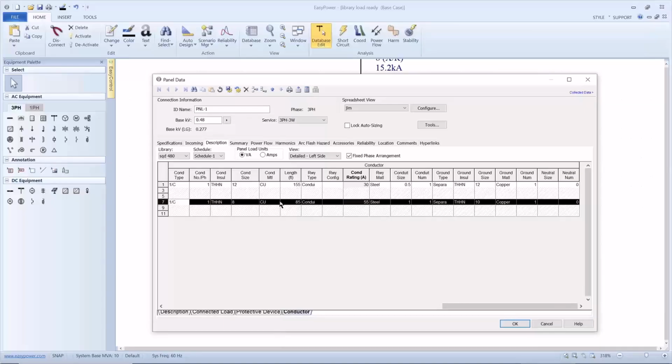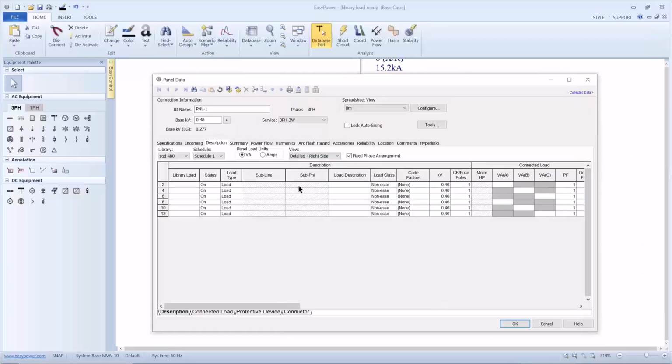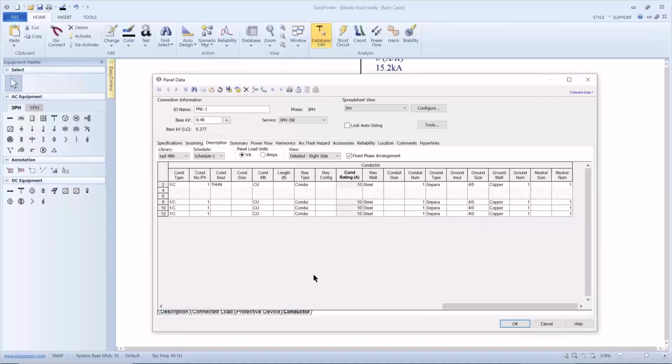Now, let's say for now, this is all the load I want to stipulate. I can go ahead and put in, say, a fixed load for the right side. Let's say it's heaters, and my heaters are a 10 kilowatt load. As I tab over, you can see it's spread out the 3-phase VA phase loading. Actually, I haven't specified the conductor size.